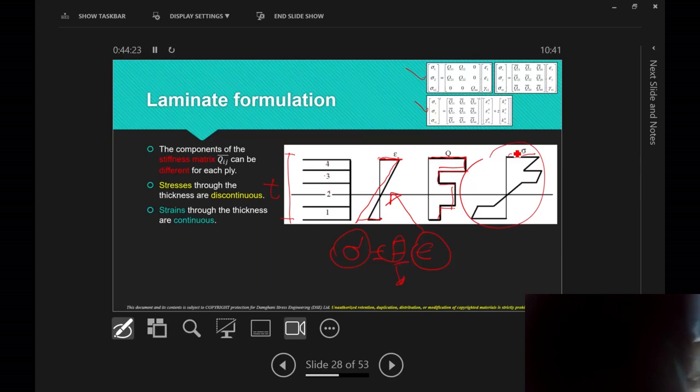Okay, it's not like metallics. So if it was aluminium, you would have strain, and you would have stress, easy, nothing to worry about. And you remember from aluminium, how would you find stress? Sigma is equal to bending moment by second moment of area. You remember that?